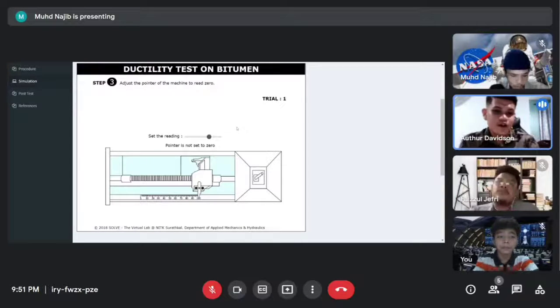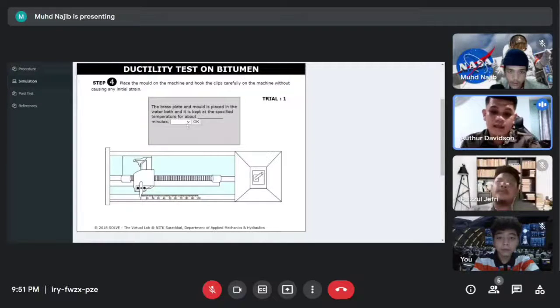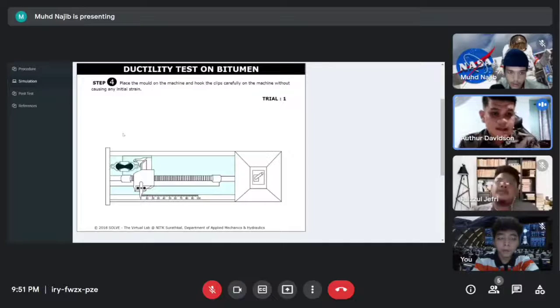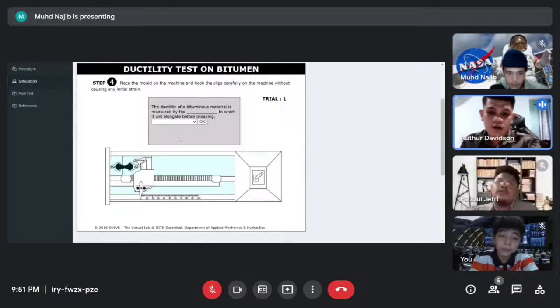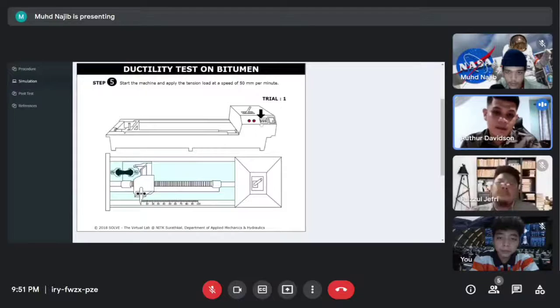Thank you, Faizul. The next step is first we have to remove the test specimen from the plate by a shearing action between the specimen and plate, avoiding any bending of the test specimen. Detach the side pieces and attach the specimen to the pins. As we can see in the visual, we attach the pin. Then we position the crosshead and ensure that the load cells are attached to the specimen. Set the elongation rate to 5 cm per minute.